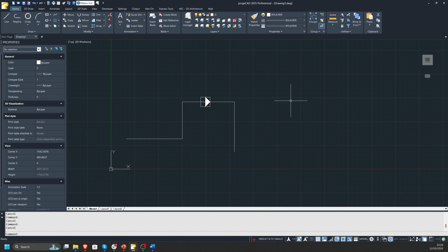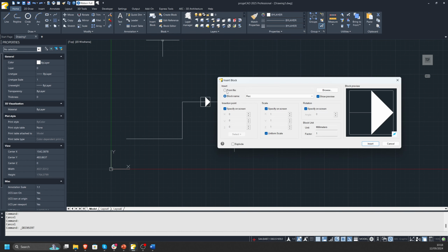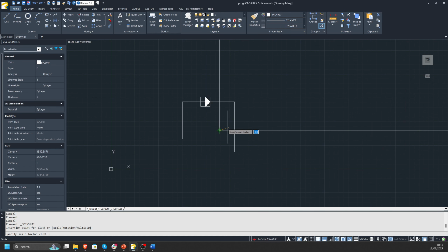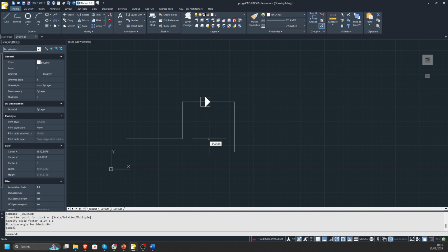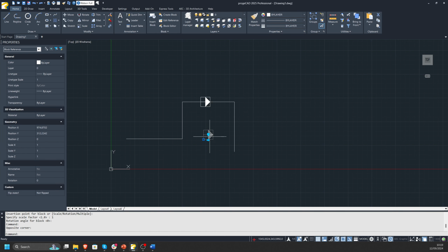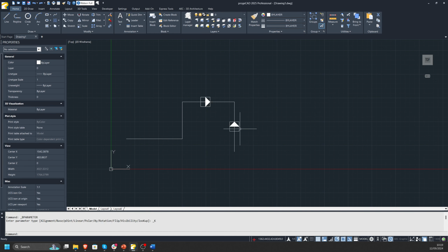So in the disk, open the disk by the side, so you have a little library. And also if you want to insert them back in, just go insert block, find it from the file you saved it to, or if you already inserted it, here you can have a block name, insert it and just put it where you want. You need the scale. Let's do it again. Insert, put it here. Scale is 1, rotation is 0, and now we can play again with our block. It's much easier than drawing it again or copying some blocks that you have saved somewhere.